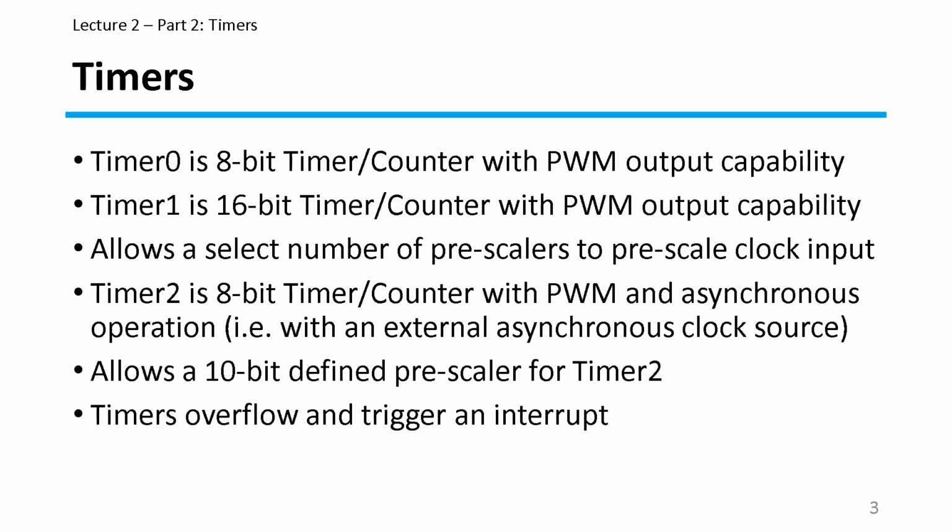Now timers work by continually counting up until they overflow. For example, in an 8-bit system, there is only counting from 0 to 255. Once the timer is at 255 and the clock ticks up, your timer overflows. Similarly, with a 16-bit timer, you are allowed 65,535, and at the next clock cycle, that timer will overflow. Now, when a timer overflows, it triggers an interrupt, and it doesn't reset the timer when an interrupt occurs.